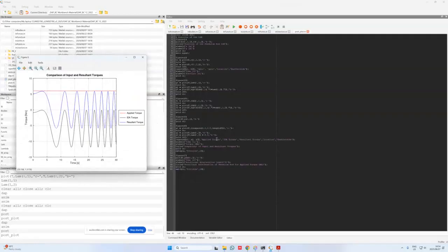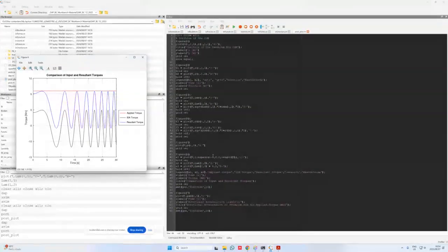If we zoom in on figure 6 over here, the inverse dynamic analysis torque is that reaction, or Lagrange multiplier, that I get from the driver constraint. So Lagrange multiplier 3 essentially corresponds to the torque that is caused by the relative rotation driver that I now specified.